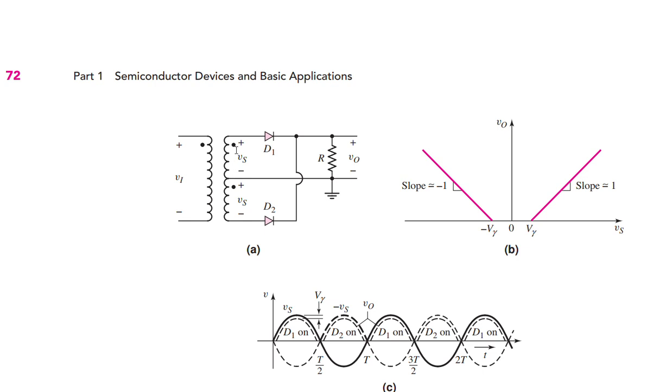So you see that we have a transformer. It's a special type of transformer which has 3 terminals, and the center tap is generally connected to the ground or the reference node. So the distinctive feature of this transformer is that for the input cycle, we have a sinusoidal voltage at the input on the primary side. There are 2 polarities of the output voltage.